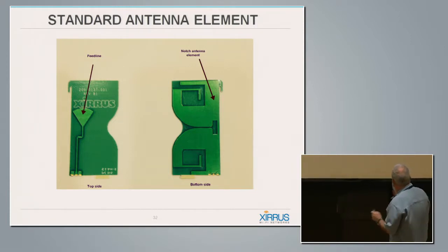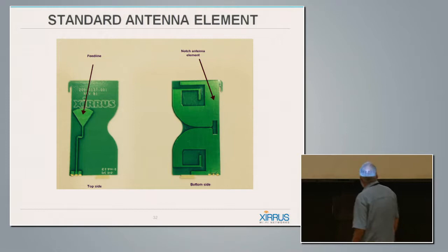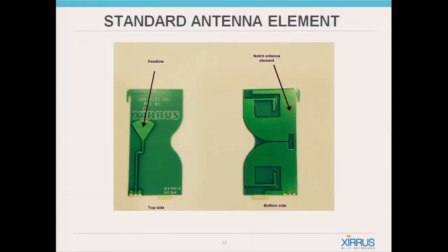And unfortunately, because I squeeze everything, it is bent. The ends here at 2.4 gigahertz, these are the extra resonators to make the antenna resonate at 2.4 gigahertz. So you can see everything is folded, everything is squeezed in order to fit it within a given space.